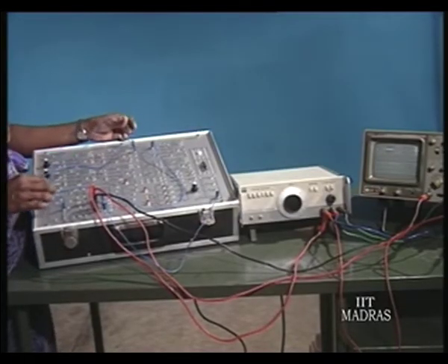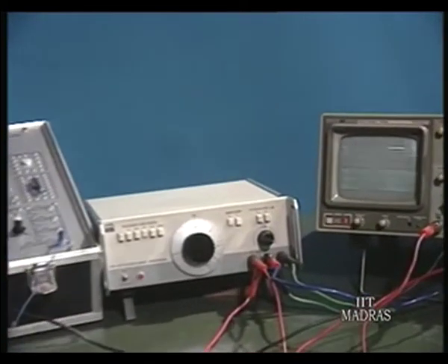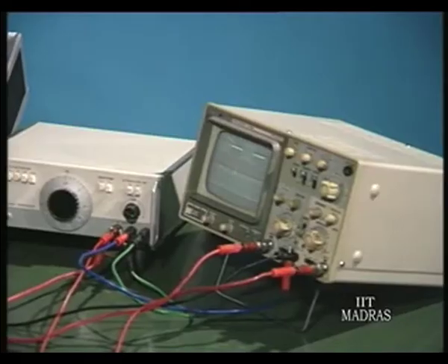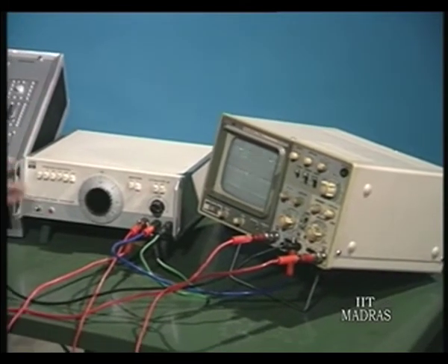On the screen you can now see she has connected a multiplier input. One input corresponds to a modulating frequency of 100 hertz, another corresponds to the carrier, which can be varied, of course, but is kept at about 1 kilohertz. You can see the lower one corresponds to the carrier, the upper one is the output of the multiplier, and since these frequencies are not very stable, it can be triggering only one waveform properly. We see that kind of movement there.